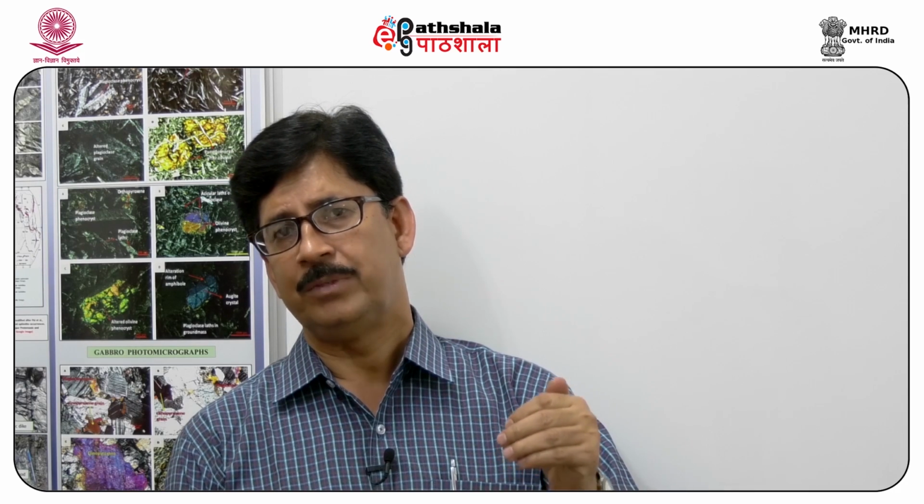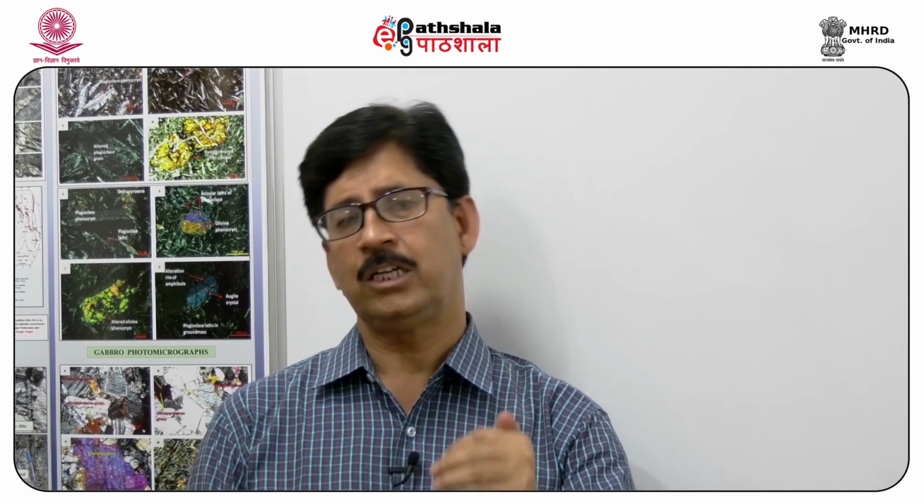For this, we have to make structures which are called dikes or groins. These are structures just like a wall, made perpendicular to the shoreline so that they can stop the sediment coming from longshore currents, especially longshore currents. Longshore currents are those currents which are the result of deflection of waves from the shoreline or coastline.